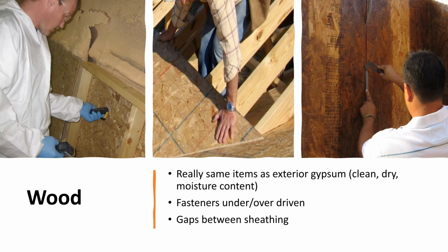There might be a reference here, but nothing that says if you're putting on this air barrier, this concrete masonry unit has to be 10% or less, or the gypsum has to be 10% or less. It doesn't exist. We've done a lot of research to find it. So we're trying to figure out what direction we can get, and we're going to try to do some research on it, because it simply doesn't exist, right? So it ends up being like, hey, let's install some stuff, let's hope it works. Maybe we can do some testing, but there isn't a definitive maximum moisture content with a lot of these surfaces.